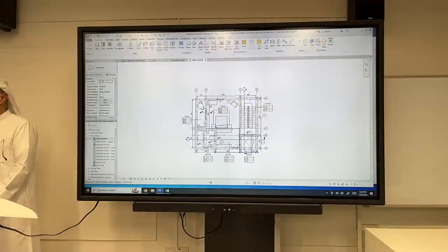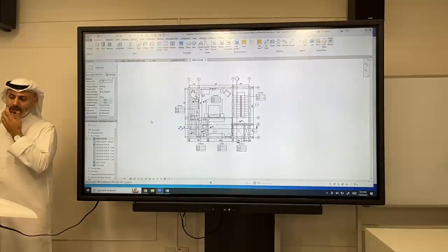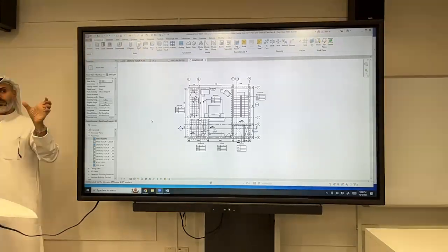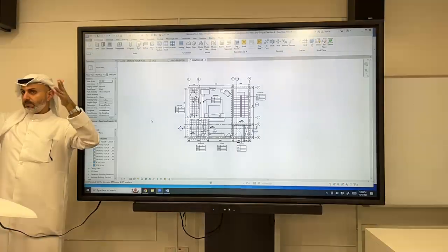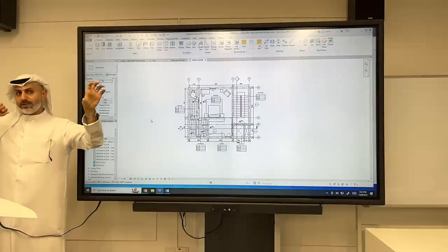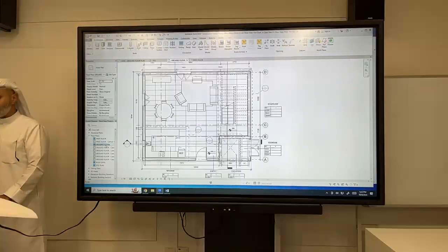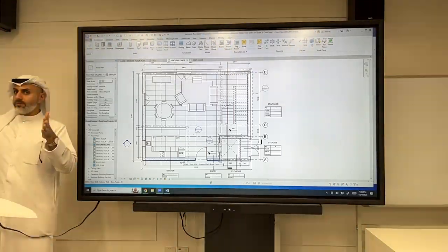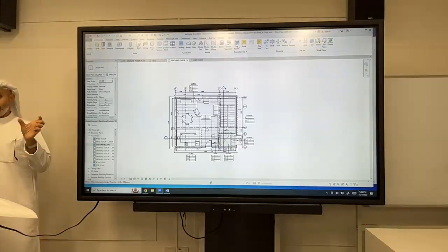Okay, let me talk about the accent wall. What I want us to do is have one part of the exterior wall, from the ground floor to the first floor, be a different material. Okay, I want to show two types of core materials. It's CMU, black block, white block. Now, it doesn't matter where, but don't put it where there's, for example, half a door or half a window. Keep clear of openings.